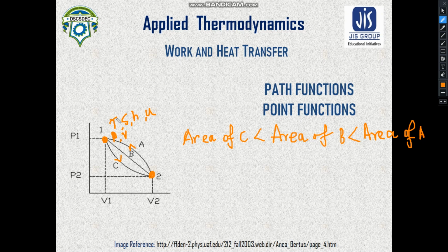You can easily say that for the thermodynamic properties, the state values, the cyclic integral is 0. So there will be no change when a cyclic process is going on. Whereas this doesn't hold for the functions which depend on the path. It can be a cyclic process, but the integral can be 0 or it cannot be 0. It doesn't depend on the states. I hope I have made it clear to you.